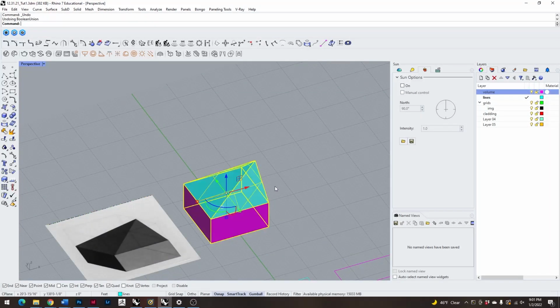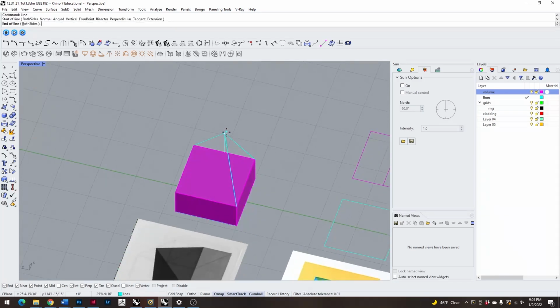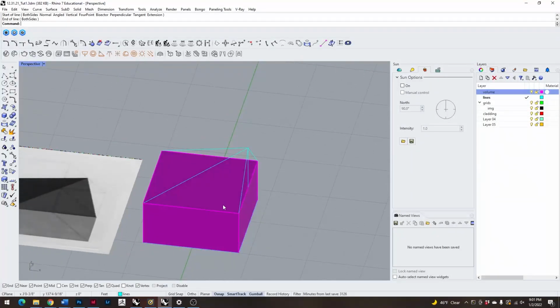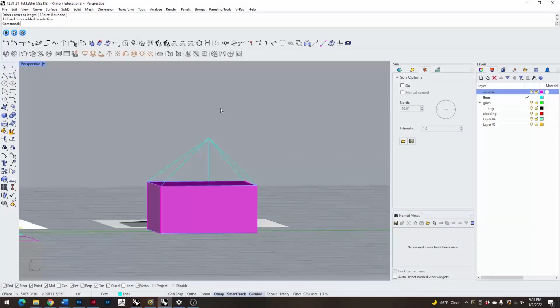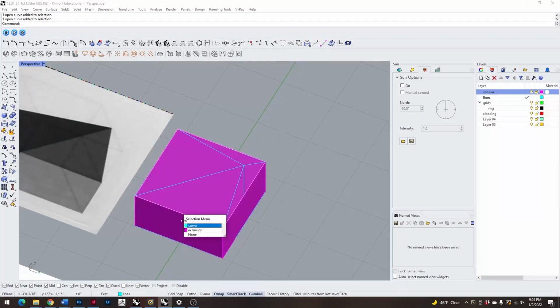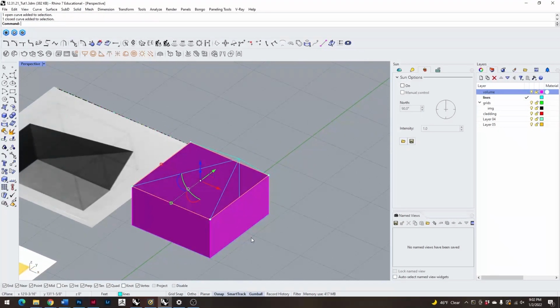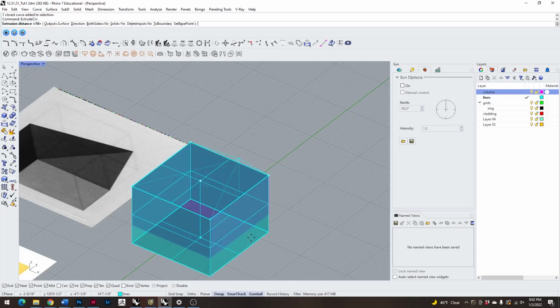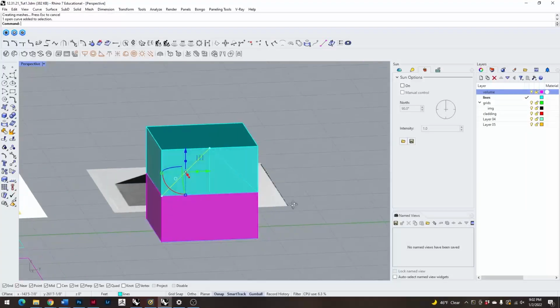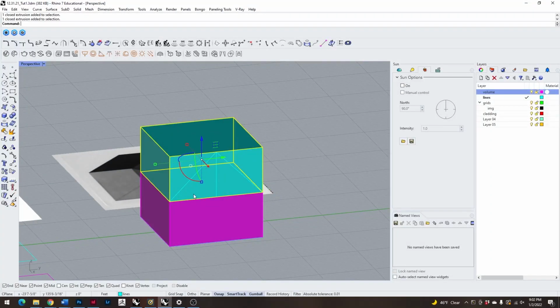The other way that we could have made this is by creating a rectangular volume. So I'll use curves and define another rectangle, and then we could cut that volume with these diagonal lines. I'll take you through the process of doing that. What we'll want to do is extrude this curve up 10 feet to make a volume.